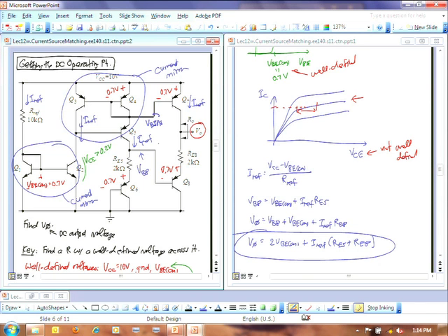You look for current mirrors. And if you can find a current mirror, you're probably going to find something that's generating current, like this side right here. You find that current, and then you mirror that current everywhere. You determine the different voltages based on your known voltages, which are the VBE ons, and the voltage across resistors when you know the current going through them.